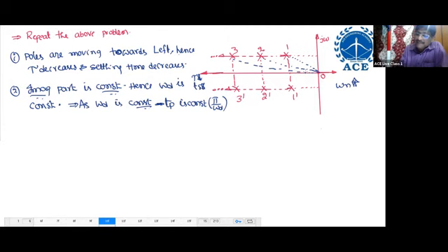This is theta 1, very large. This is theta 3, very small. So zeta equals cos theta. Theta is decreasing. Cos 0 means 1, and zeta increases. Zeta increase means percentage of MP decreases. The system is more relatively stable.